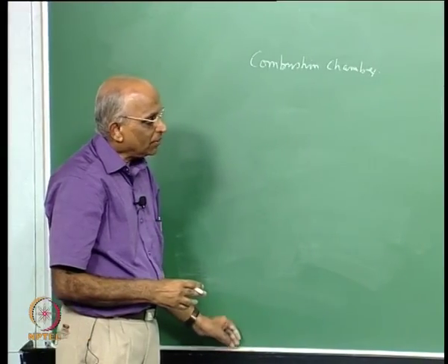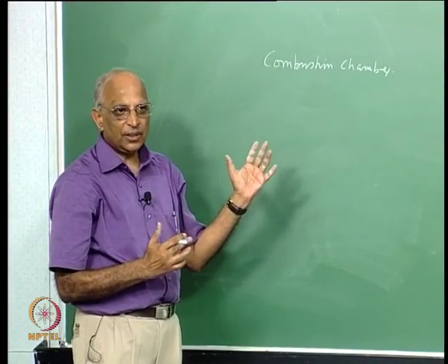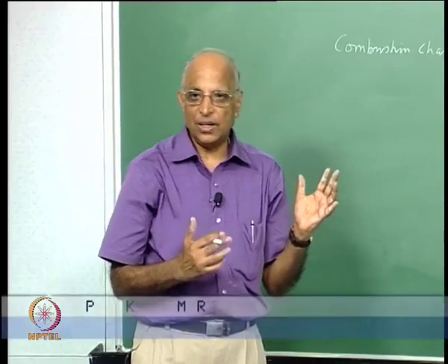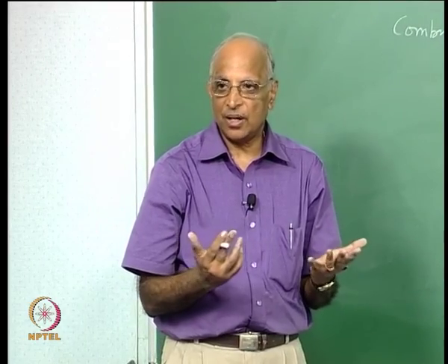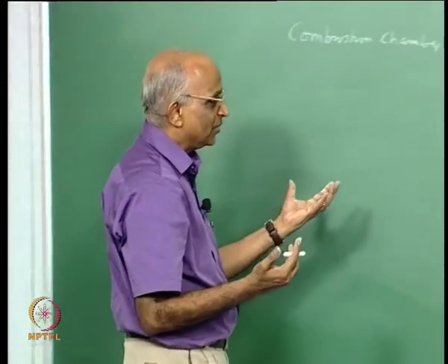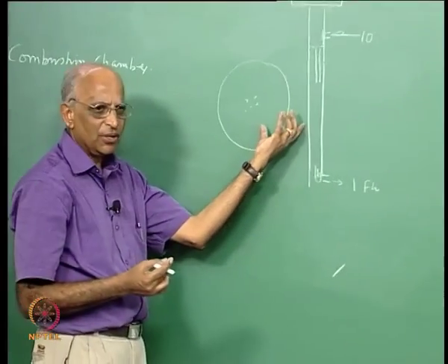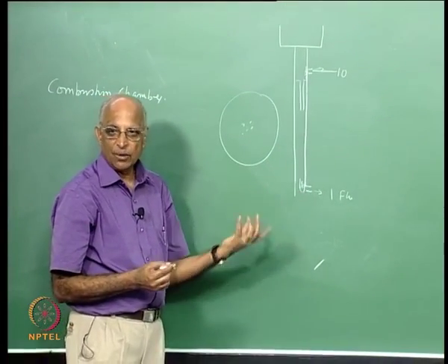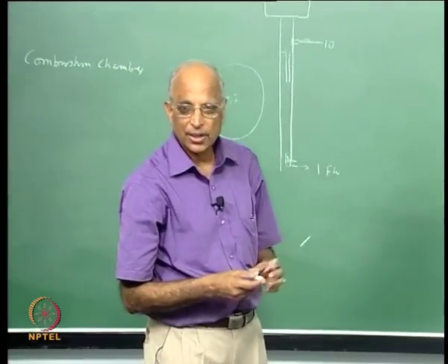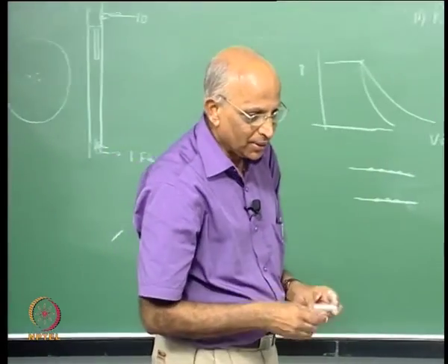Therefore, in this class what is it we have done? We started with the gas generator cycle. We looked at the deficiencies of a gas generator cycle, namely some propellant gets wasted which is not fully utilized. Therefore, a staged combustion cycle and expander cycle are preferred, especially at high pressures. Then we just started with the injectors, we looked at the showerhead injectors. Maybe we will build upon this and look at the other injectors which are used in liquid propellant rockets in the next class, right. Well, thank you then, I think that is about it.